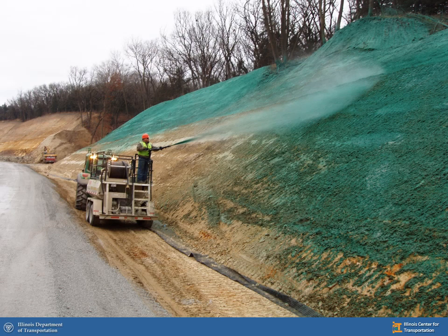Here we go. We are hydro seeding, right? We're painting this slope green with seed, mulch, and nutrients all at the same time. You can notice that we're applying this up the slope, and we have a baseline down here. So when we're taking our measurements, if we go to Article 250, which is seeding, we would see that all measurements should be taken along the slope. We're going to have to take several measurements where the slope changes, and then plot out our shape and make our calculation on area.